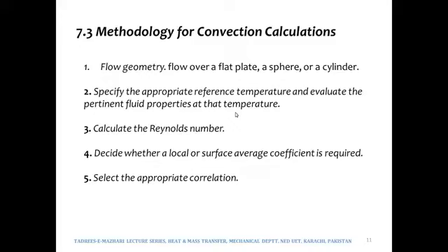So over here point number 2 means that we need to calculate the fluid properties such as Prandtl number, such as diffusivity, such as conductivity, because all those properties would be required in the calculation of Reynolds number and Prandtl number, which will be used in the calculation of Nusselt number, because we have seen at various points in the previous slides that we have the expressions of Nusselt number in terms of Reynolds number and Prandtl number, right?